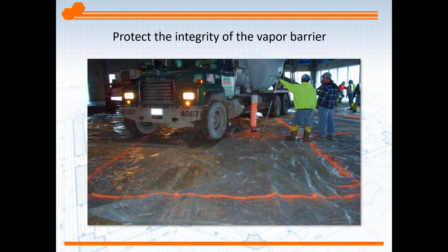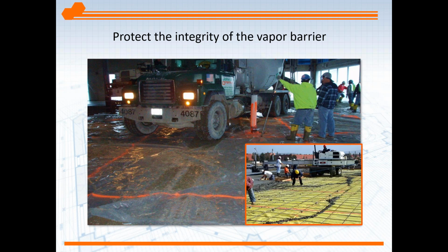You've got a several-ton ready-mix truck driving over this plastic, and as those pneumatic tires roll over the plastic, possibly shearing along as they roll across the surface, you're introducing pinholes. So you've just defeated the benefit of that moisture barrier by driving a ready-mix truck over it. And sort of the same issue here. We've got a laser-mounted screed, pneumatic tires driving over that moisture membrane. Are you popping holes in it?